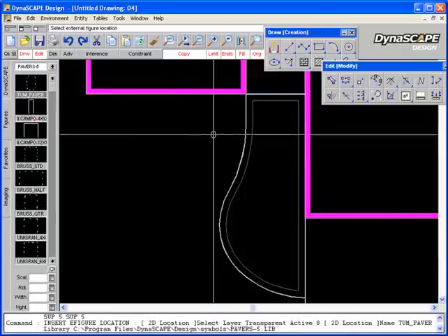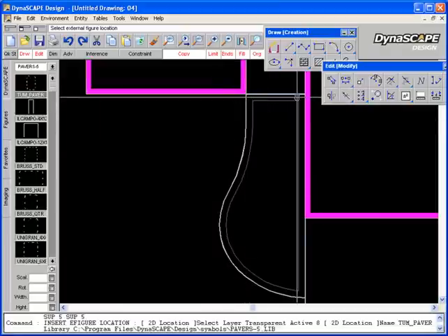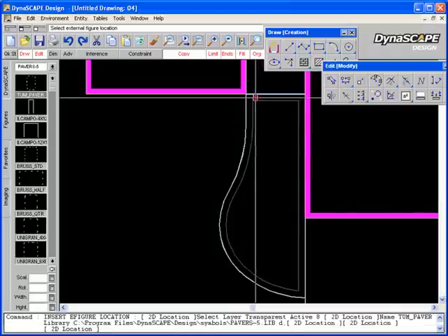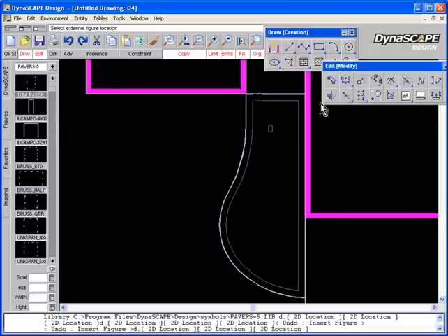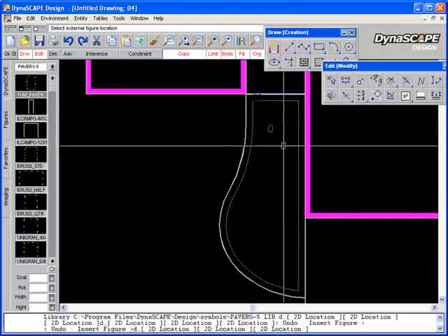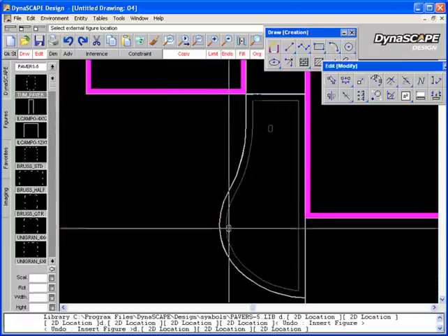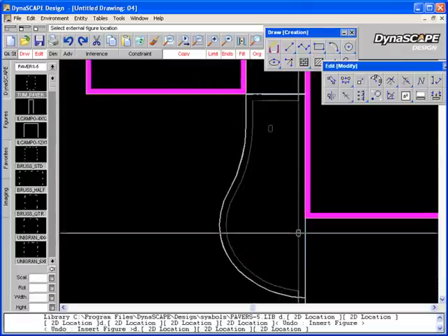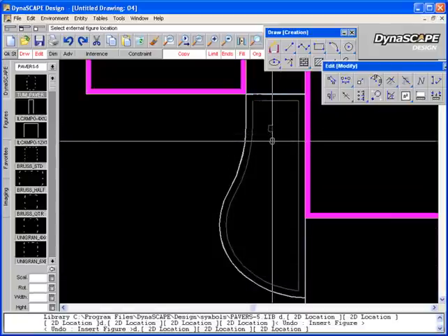I like this brick mainly because it has an insertion point right in the middle, and I'm going to put this along the outside. Now the slow way would be to drop them in one at a time like that, which is really hard to do. We're going to use the offset figures tool to create this soldier course. What I want to have is a continuous line around the outside in the middle of my soldier course, because that's where my insertion point is on my brick here.